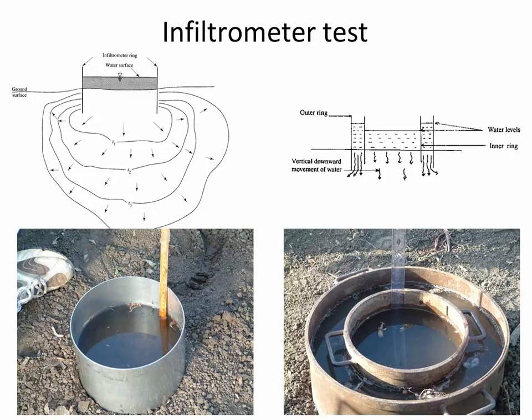Here, this isn't a real rainstorm. This is just a test that we can then empirically correlate, how it behaved for the infiltrometer to how it behaves when actual raindrops are falling onto the soil. Some of the differences, if you think about a storm compared to this depth: during a storm there won't instantly, from the very beginning, be 6 inches of water on top of the soil. That's not realistic, that there would be instant ponding.